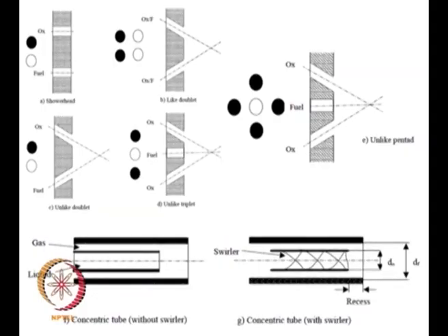So then it is easier to have this kind of injector wherein it is coaxial. You will have the liquid in the core and the gas on the periphery. You could also swirl the inner fluid, that is the liquid, and you will get a swirl injector. So for coaxial injectors, you will have many of these repeated, right. Each is one unit and you can repeat it to get your overall injector.